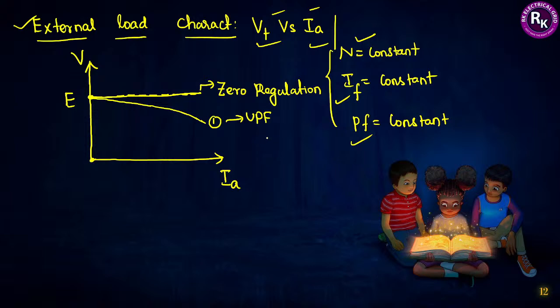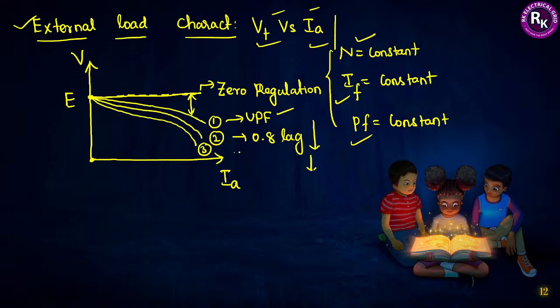And suppose our alternator is being operated at not unity power factor but a slightly lower, 0.8 lagging power factor, then your curve will droop again. The second one will be talking about 0.8, practically, that is 0.8 lagging power factor. Still, if you are trying to lower the power factor further, we are going towards more and more lagging. I started at unity power factor. We are observing only the resistive and reactance drop. After that, if you operate the alternator at a lagging power factor, then again your curve will droop. Again, if I decrease it to 0.5 or 0.6, it will decrease again.